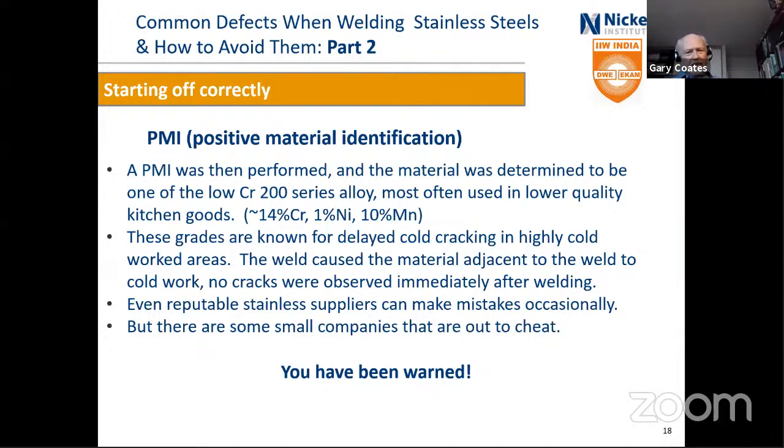And then in the case of this particular tank, in the cold worked area, which was the heat affected zone, it wasn't the heat that caused it. When a weld cools and shrinks, it stresses the heat affected zone to very high levels, maybe even 100% of the yield strength. And the cracks were not observed immediately after welding. They were only seen after the hydro test. There were tiny, tiny cracks that weren't visible, and then they opened up with time.